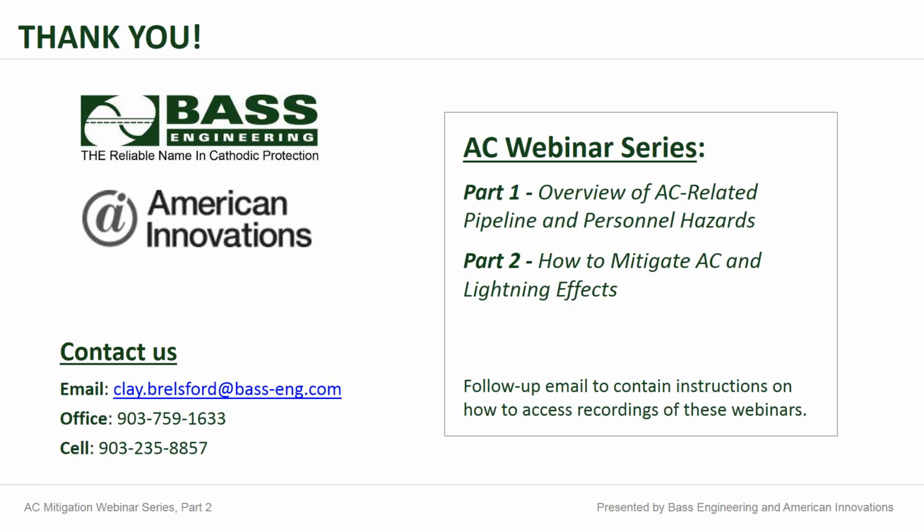Thanks, Clay. And for our last question of the day, wouldn't a casing being used as an AC drainage point face accelerated corrosion? The short answer is yes. You would be intentionally corroding your road casing if you used it as a part of your AC mitigation system.